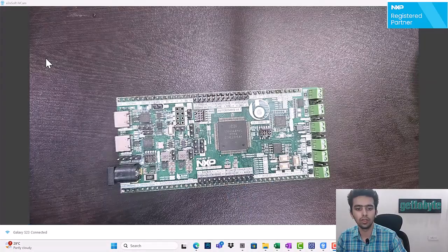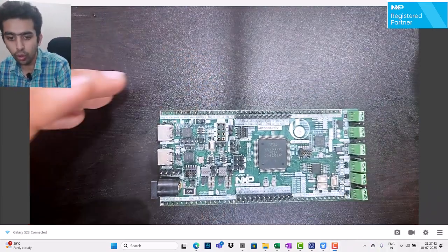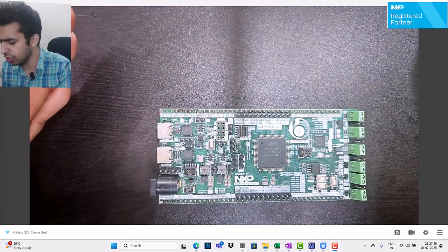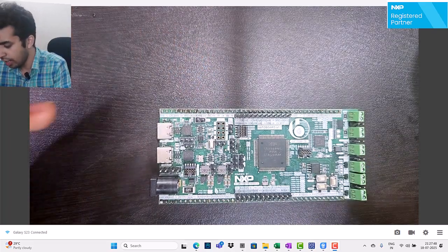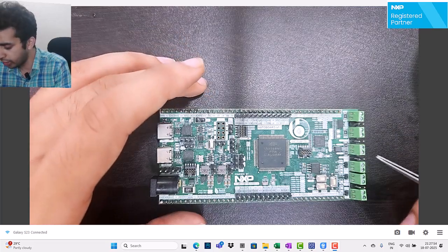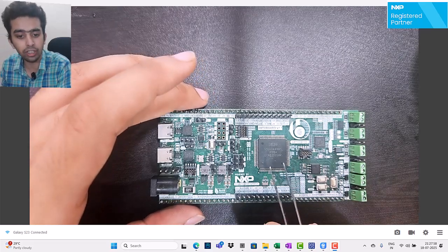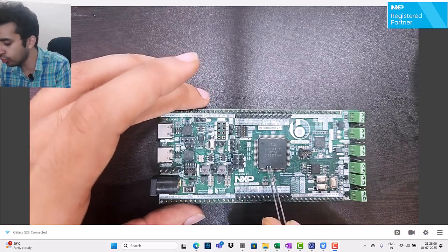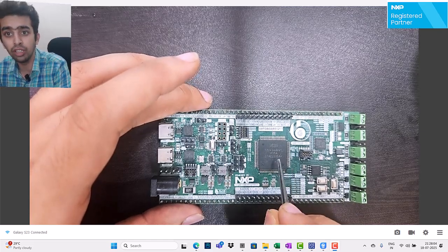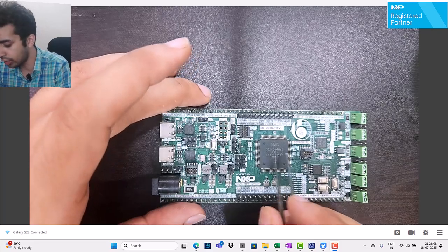Now let's take a closer look at the Gettobyte Technologies Autoboard version 1.1 board, which is specifically designed and developed for industrial and automotive applications, having communication protocol support on board like CAN, Ethernet, and LIN. At the center of it is a powerful NXP Semiconductors S32K344 MCU, having the inbuilt Ethernet MAC peripheral, which enables using Ethernet via the chip by just connecting the Ethernet PHY ICs.